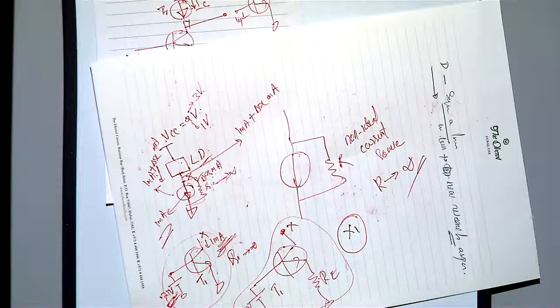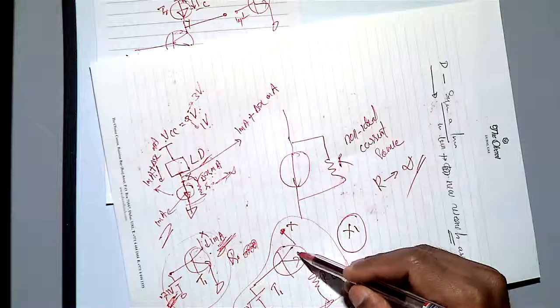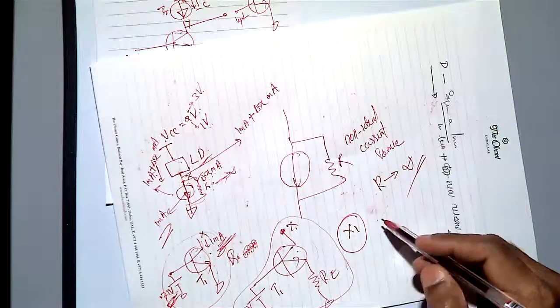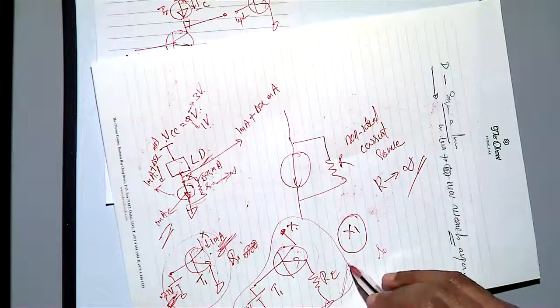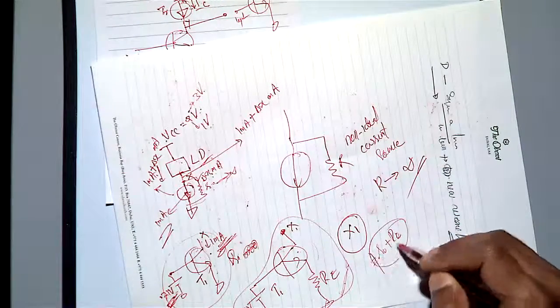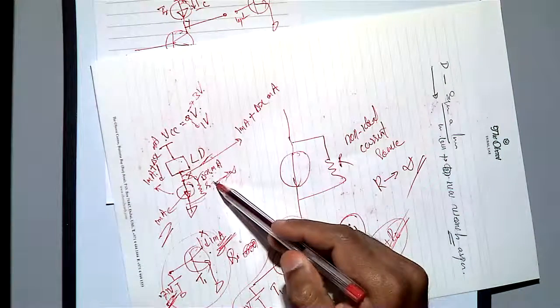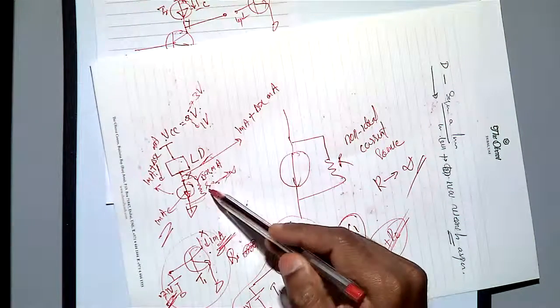Much better, because here your impedance is equal to RO. So what is your impedance here? Yeah, here the value is much bigger, not simply RO plus RE. Actually, this is much bigger than 1 plus beta times. So actually we are increasing the impedance of this current source.